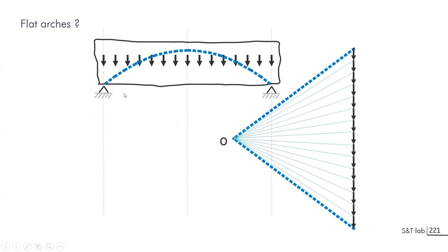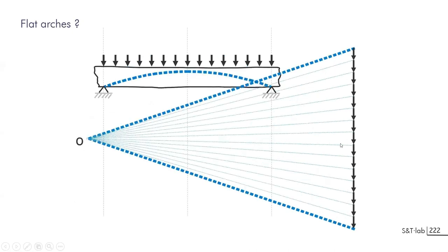The fact is that if it remains quite flat, the horizontal force will be very important, as we have seen in the Vessy bridge from Robert Maillart, and you are not sure that the support won't be moving. In this case, something happened, and you will need these tension forces below the beam to equilibrate the system. And this will drive you to a bending system.